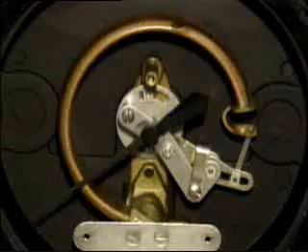Many of the instruments used to measure pressure contain devices called pressure elements. Basically, pressure elements sense changes in pressure and convert those changes to mechanical motion. Three of the most common pressure elements are bourdon tubes, bellows, and diaphragms.